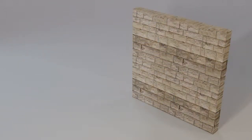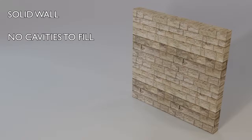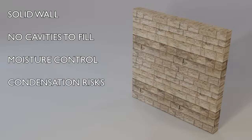In contrast to a framed wall, a solid wall very rarely has a substantial cavity to work with, so any meaningful increase in thermal performance will necessitate increasing the wall thickness. The type and location of this increased thickness can lead to significant differences in performance, as can the nature of the base wall. In this type of wall, particularly when placing insulation internally, getting the right moisture control strategy is important, as if the dew point and condensation risk is not properly managed, it can lead to substantial problems.